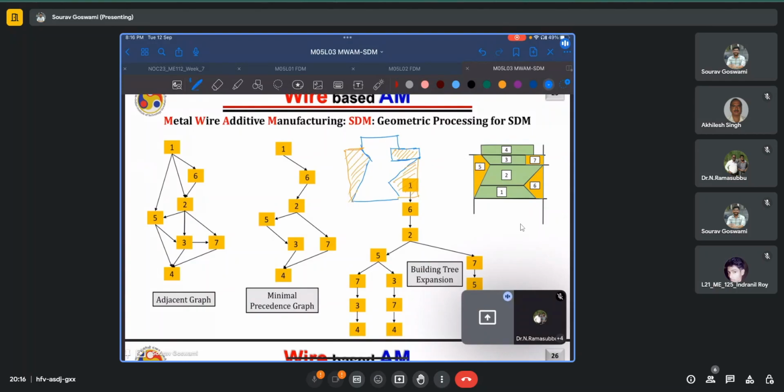And we identified the regions where we are supposed to segment it along, the segmenting planes or the part decomposition planes. So here we find that the non-overhang region is changing to the overhang. So one of the planes can be here. Of course, this plane can also segment the support structure. The second region was encountered here, where it was found that now this region is becoming overhanging. The third plane was here, where you have an overhang in this region, and so on.